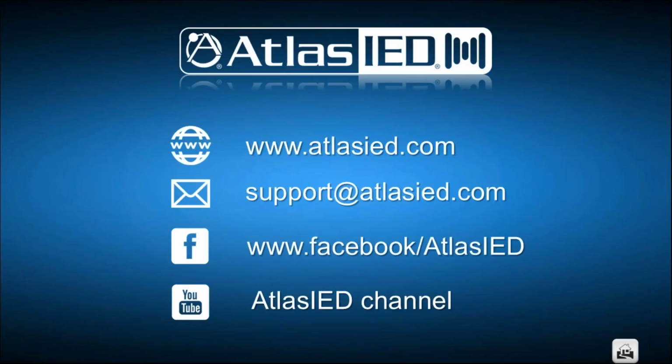But yeah, if anybody has any questions or comments, feel free to reach me. The information we do need if you are trying to provide a sound masking solution is a decent floor plan, a PDF file or a CAD drawing. This is the information that will be requested through the website at the support tab: a clean PDF or CAD file, the ceiling height from the floor to the grid, the type of ceiling grid material you have, be it gypsum board or acoustical ceiling tile, and also the plenum height from the deck to the ceiling grid.